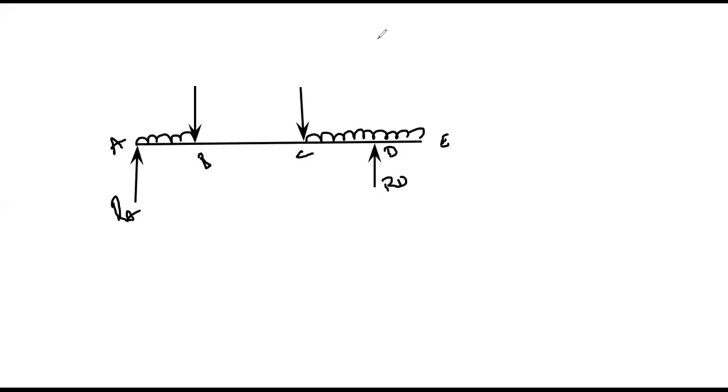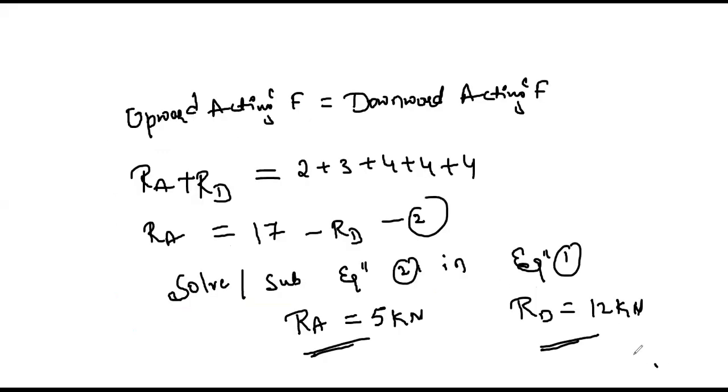To draw the shear forces, first I should take a reference line parallel to this beam. Then I need to mark the points. So parallel to this, this will be A, this will be B over here. This point will locate here. This is D, this is E. Clear?